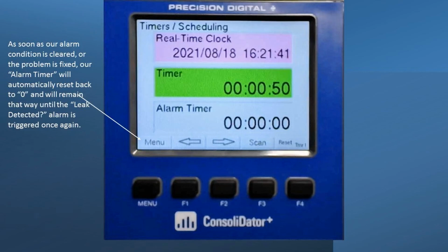Someone had asked me about the inputs when it comes to the frequency or the speed measurements. So I've mentioned before that the pulse inputs on the device can be used as a digital or discrete input. The inverse is not true. What I mean is when we're talking about using this as a tachometer, we're going to want to use the true pulse inputs, not the discrete or digital inputs. So that's a good distinction. That was a great question.